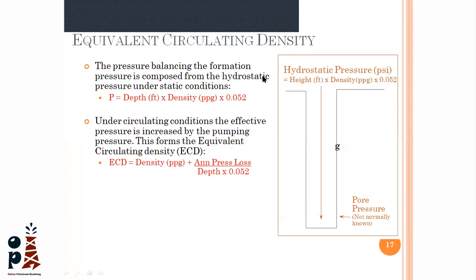While we are mixing, it is my responsibility to provide the mixing recipe. So I have to calculate the mixing recipe. But for the pressure and the mud weight, as I told you, it is the most important thing, and it is the pressure control. So we get this from the drilling company or from the company that has the well itself. We call it the operating company. The operating company provides the mud weight calculation and pore pressure calculation for us in the drilling program.